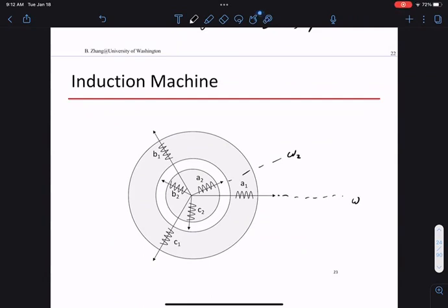There is a torque making the rotor rotate. But then what happens is you create this angle called theta 2, depending on the different speed of rotation at each pass. Because this angle depends on the speed of rotation, different angles create slightly different circuits and different spacing between the inductors. Because of different angles, inductors are at different distances from each other, so that's why the inductance changes in this circuit. I have a different rotation speed, I have a different angle, and things change.